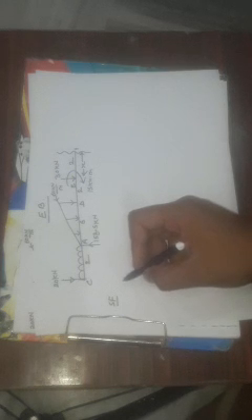Now the next portion is EB. The loading diagram for EB will be like this, just left off. We will take a section. This point load and this 15 kilonewton meter couple are included in the loading diagram. Write the shear force equation for this portion.